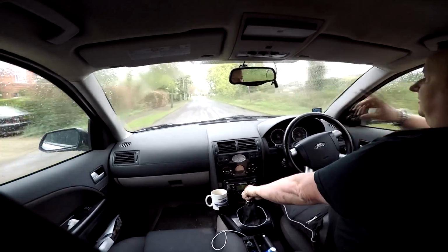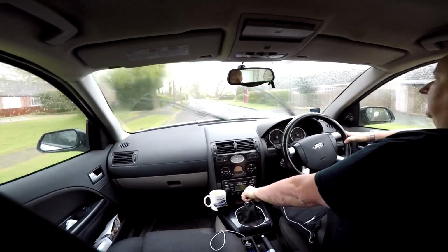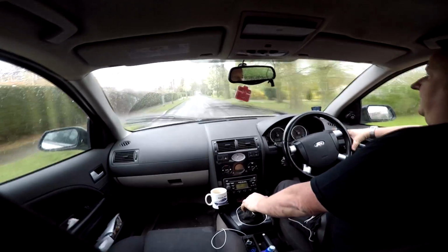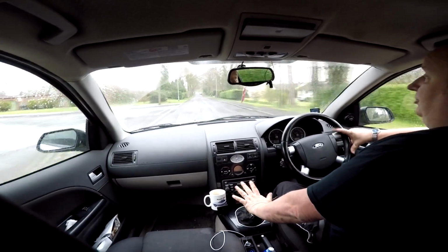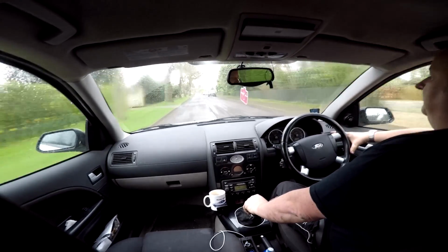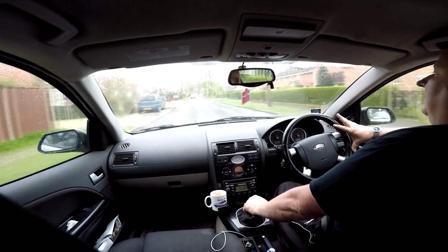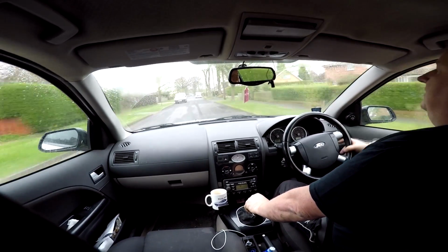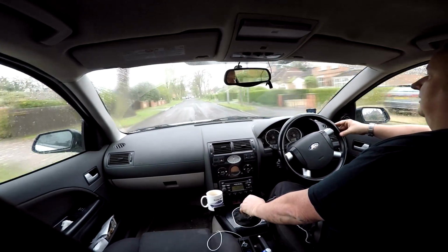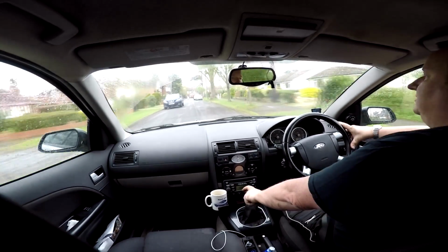Now, although I say normal driving, there's a bit of hesitation when I put my toe down a bit, like fuel restriction. Now I'm going to go round again, because as I say, I'm not sure. I'm thinking now, if the fuel pump had a problem with the voltage, in other words, one of the connectors, I'd possibly be getting this all the time. But as you can see, normal driving, don't seem to be a problem.